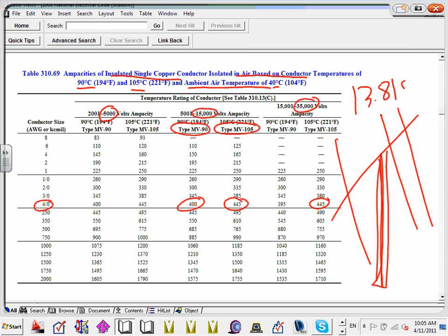Suppose I'm going to be using a 34.5 kV system. That's another system that they use, 34.5. It will sit you right in here. Suppose I decided, because I don't care about money, I will use this insulation. You can use either. By the way, 105, the only difference is more money on 105. You can get 445 amps from a 4-aught cable. Any questions, guys, about this?